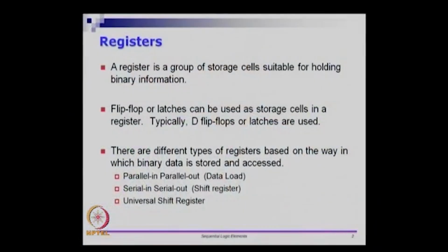The first thing I would like to talk about is something called a register. A register is just a group of cells, a collection of cells, and these cells could be either latches or flip-flops. Usually we use D latches and D flip-flops because they are fairly simple to explain and understand, and all it does is storage of data.